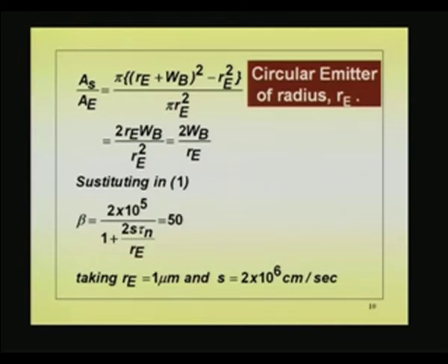If you take a device which is 1 centimeter square area, perfect, beta is 2000, you will get. But what they did in BL is, once they saw this, they realized that the effect is due to surface, because you do not see it in silicon, even in small area devices, they tried to passivate the surface.